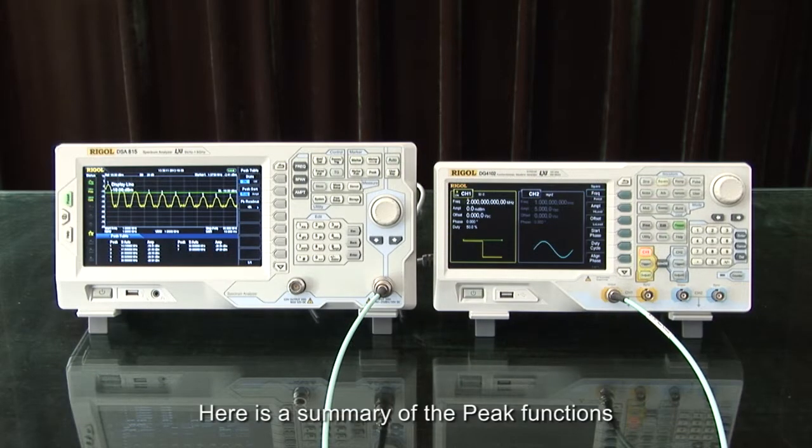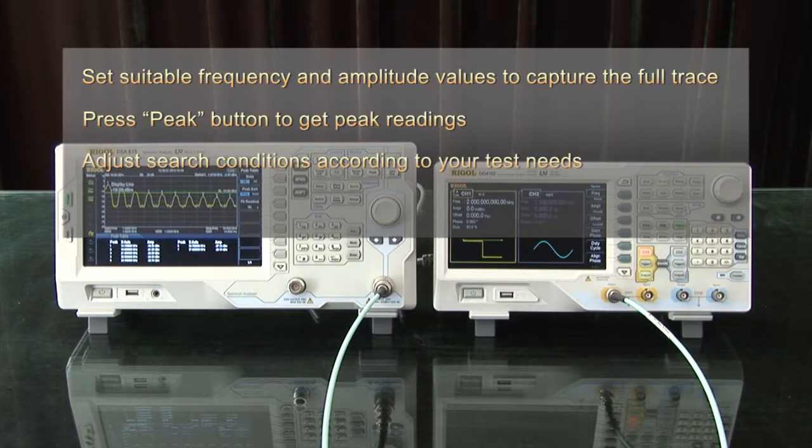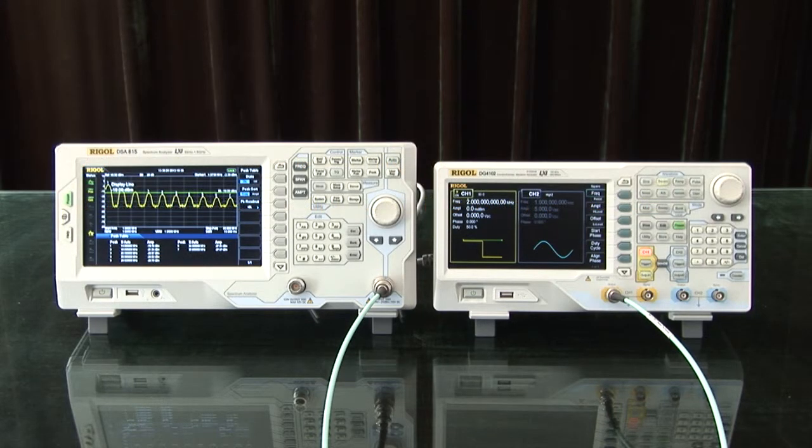Here is a summary of the peak functions. Set the suitable frequency and amplitude values to capture the full trace. Then press the peak button to get the peak readings. You can adjust search conditions according to your test needs, and then observe multi-peak readings at one time using the peak table. Thank you.